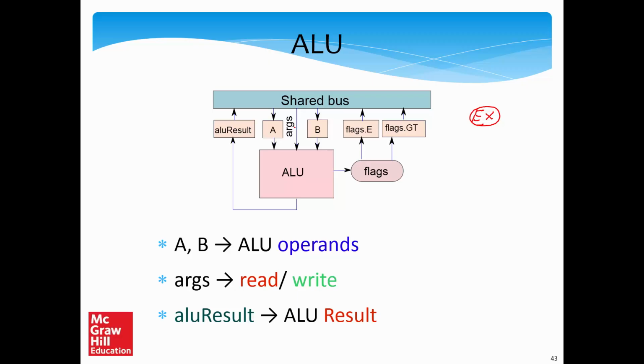If you want to perform an ALU operation, then most of the time we'll have 2 operands, like add, multiply, subtract. Sometimes we'll have 1, we'll take a look into that. So we'll add one 32-bit micro register called A, which stores the first operand. We'll have one more 32-bit micro register called B, which will store the second operand, that we will read from the shared bus.